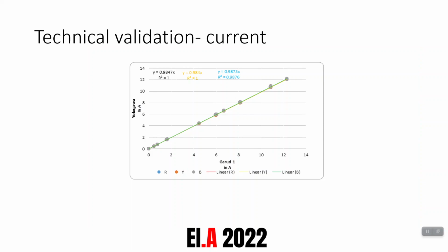Now, in order to validate and check if whatever data we've captured is correct or not, we had to compare our readings with a standard meter. So to validate that the logging system is running as expected, we ran several test routines. One test we had conducted was we checked that the electricity consumption values captured by Garud are similar to values observed in the monthly electricity bills.